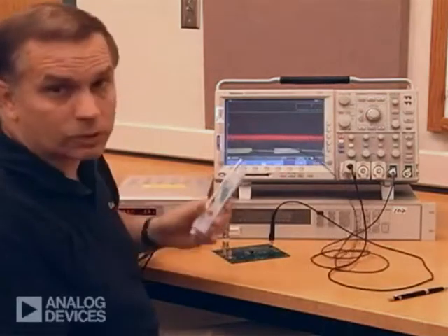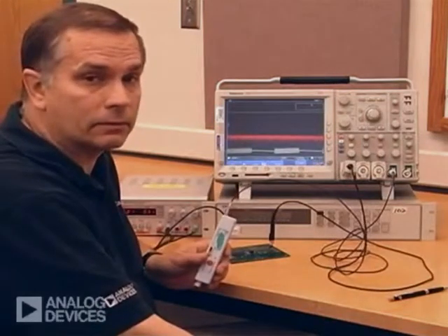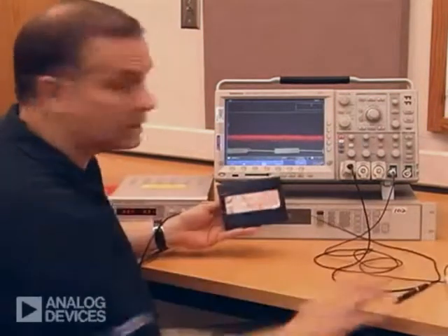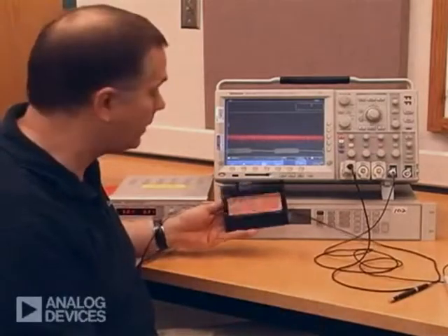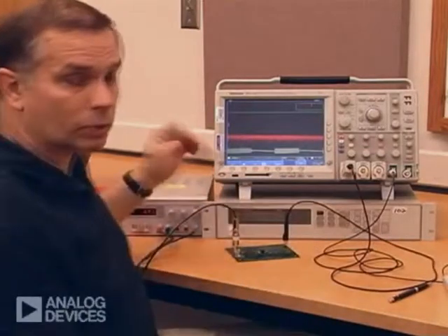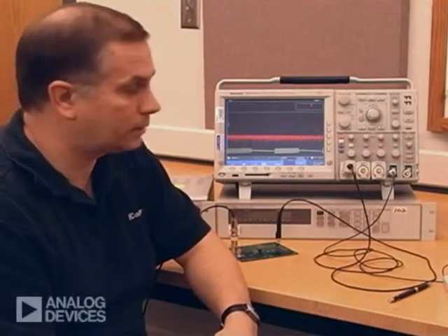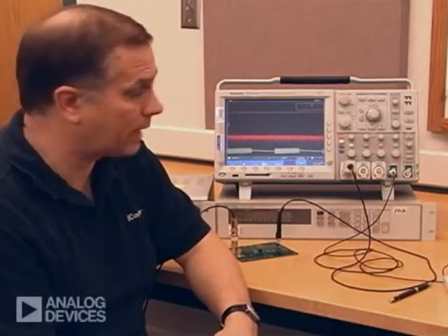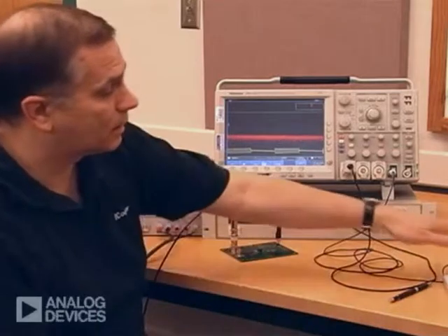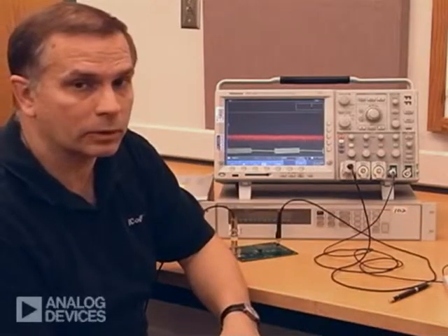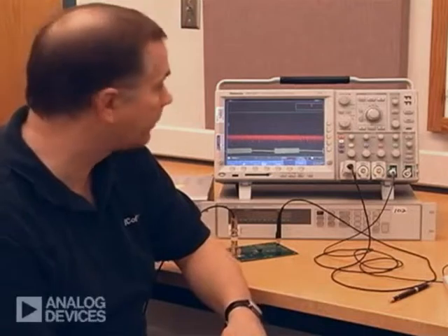It looks like a total of almost 15 dB down, just with a piece of copper tape on the backside of the board. The structure shown earlier is going to be much more effective because it's going to be well controlled, and the capacitance is going to be much higher for a smaller area because the 4 mil spacing on the board is going to improve that situation significantly.